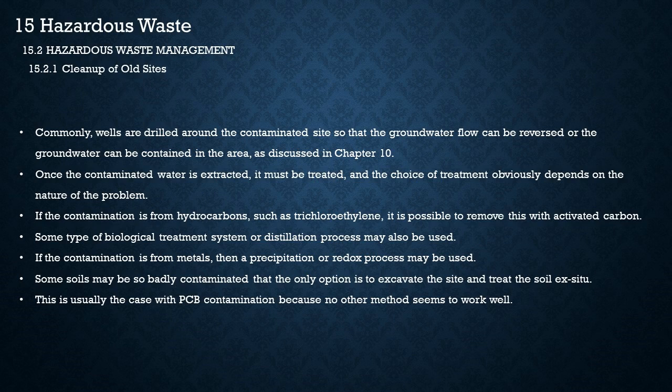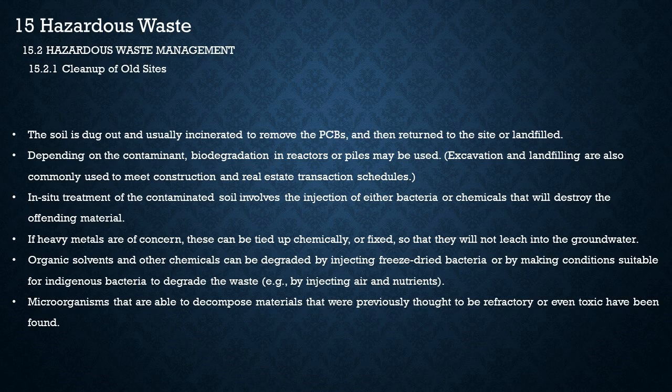Some soils may be so badly contaminated that the only option is to excavate the site and treat the soil ex situ. This is usually the case with PCB contamination because no other method seems to work well. The soil is dug out and usually incinerated to remove the PCBs and then returned to the site or landfilled. Depending on the contaminant, biodegradation in reactors or piles may be used. Excavation and landfilling are also commonly used to meet construction and real estate transaction schedules.